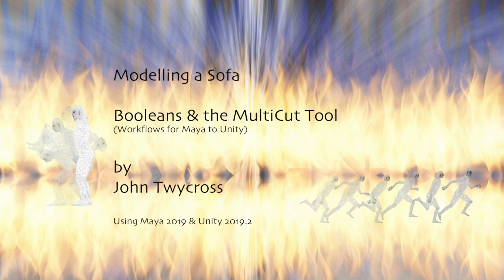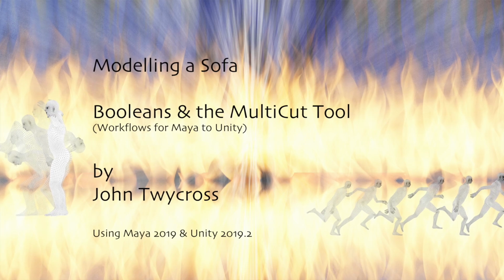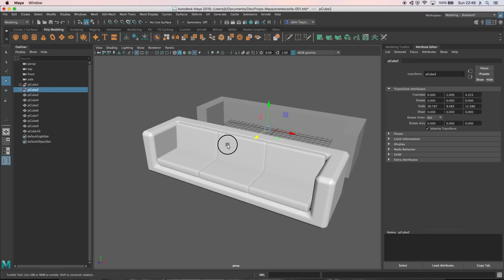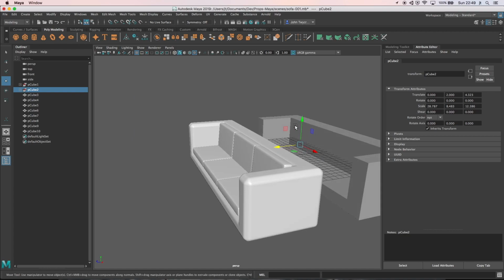I'm making furniture. I've made this example mock-up of a sofa. I'm going to do a slightly different one in this example, and I also want to demonstrate how Booleans work with this as well. So this is the original shape, but that was actually a cutout from another cube, which is actually live here. So I can see how you can adjust that cube shape by moving it around. So that's a live Boolean there.